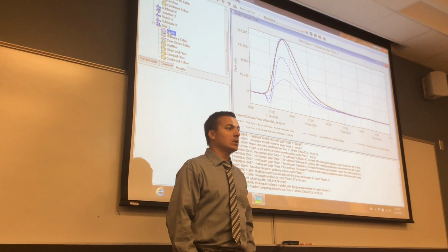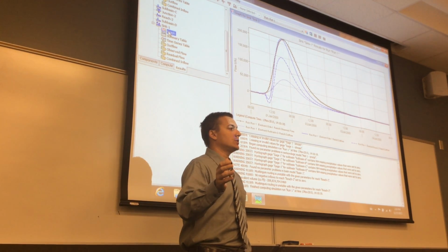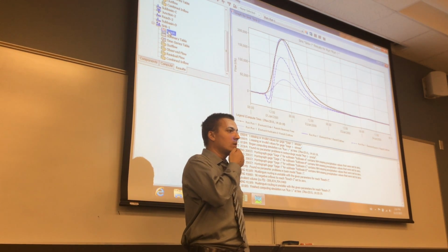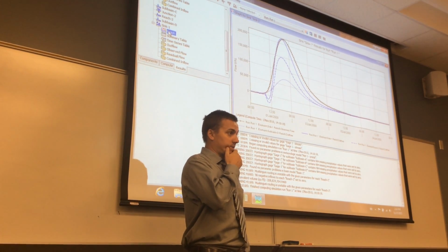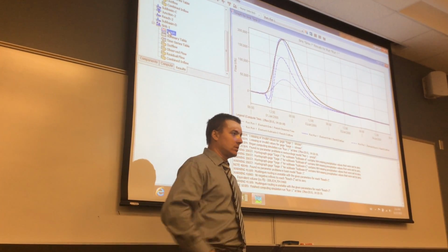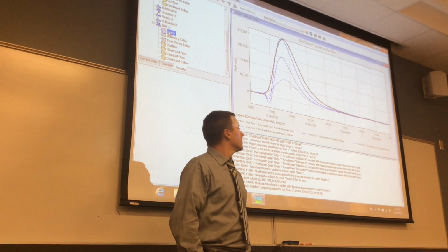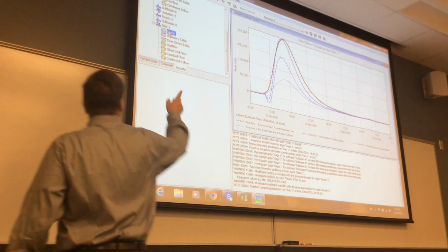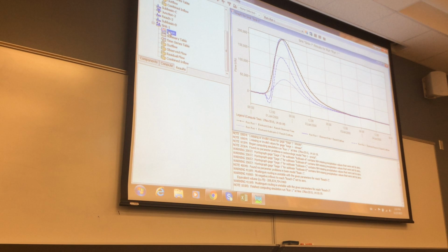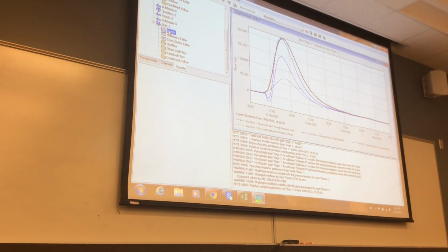Do you guys agree with what I'm saying? Yep. So if we're mainly looking at peak flow design for this bridge, we're happy. We matched what was measured, right? So the black is what we actually observed, and the blue is what the model is telling us. No, the other ones are the components that are making up the blue, which is the routing, the reach, and the rainfall runoff result of subbasin B. If you add the two dotted lines, you get the blue.